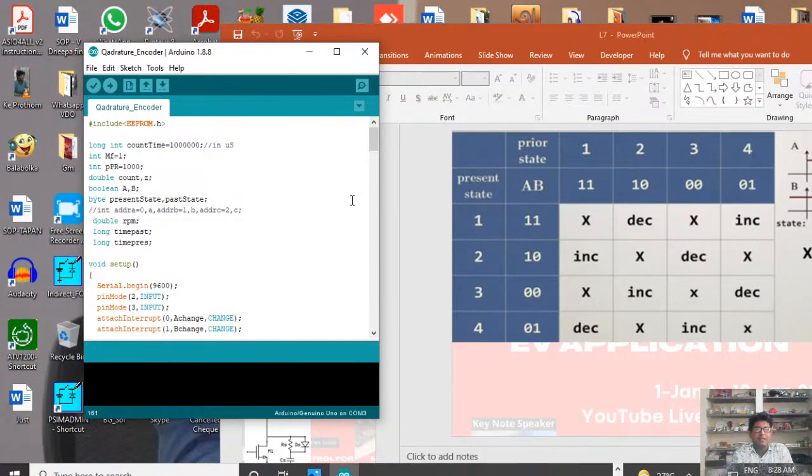where by only sensing the current, I have shown you the sensor used to sense the current, that is the LEM sensor. I think LA55, I have shown you how to connect it and how to set the measurement resistance, all these things I will show you. So you take the current, and from the current you can again estimate it. Still there will be some calculation you need not understand in this course, because I framed it that way. So that is very important.